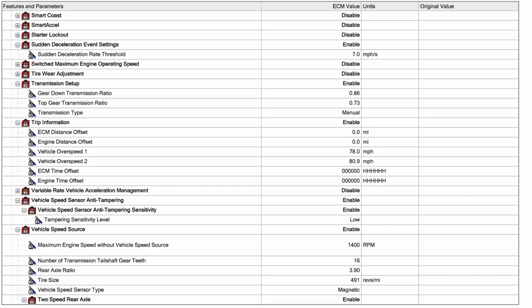Tire wear adjustment. I've never seen anybody use that. Maybe once on a fleet truck, like a Warner truck. It was turned on. All that does is fine increment adjustments to tire height to make trip mileage as accurate as possible. Okay, transmission setup.